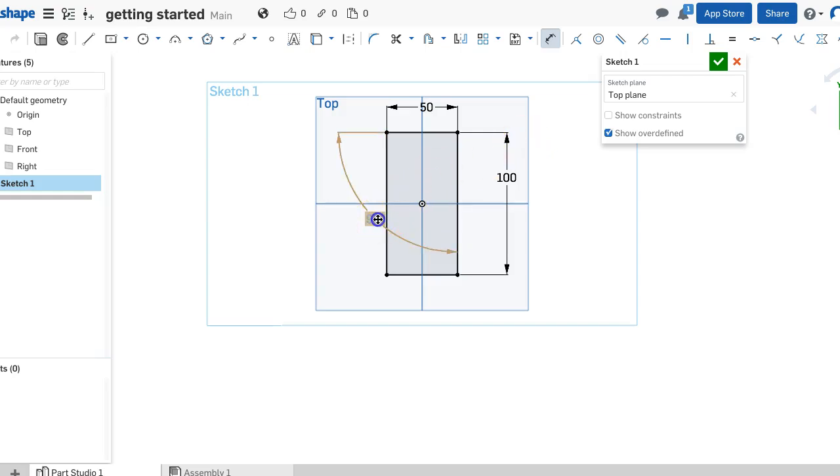And what you find out is, if you tried to change this, it's not even going to let me change it. Let's see if it'll let me change it. So let's say we change it to 85. Now you're going to see things turn red because there's a contradiction. This is a rectangle, it's perpendicular, and yet I tried to make this not be 90 degrees. So what I'm going to do is I'm going to delete that, and it will fix it. Okay, so these are kind of the basics of constraint.